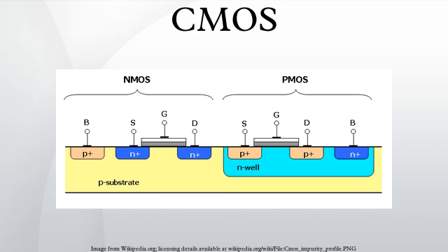If either of the A or B inputs is low, one of the NMOS transistors will not conduct, one of the PMOS transistors will, and a conductive path will be established between the output and VDD, bringing the output high. As the only configuration of the two inputs that results in a low output is when both are high, this circuit implements a NAND logic gate.